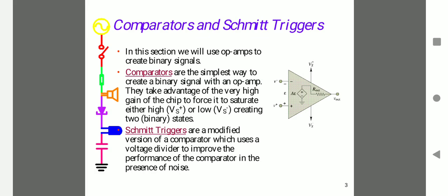Here it extracts the sign of the voltage between its two inputs. Normally the Schmitt trigger is used to convert slowly varying signals. That is, the purpose of the Schmitt trigger is to convert any regular or irregular shaped waveform into a square wave output voltage. So we also call it a squaring circuit.